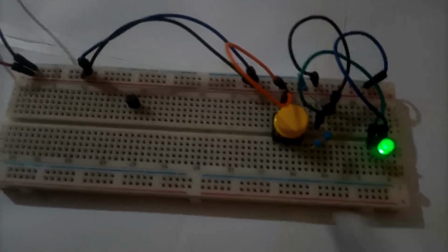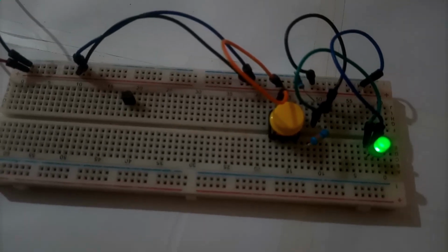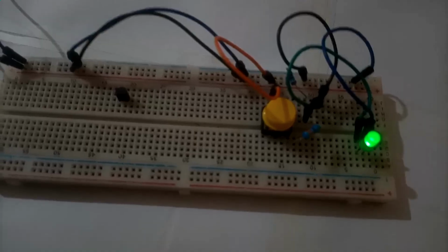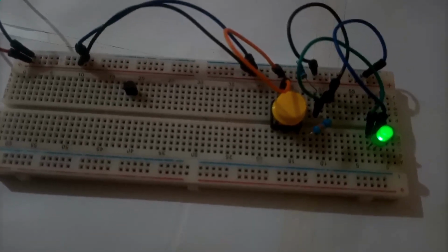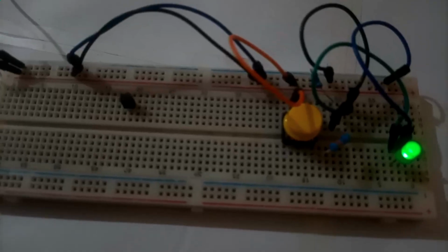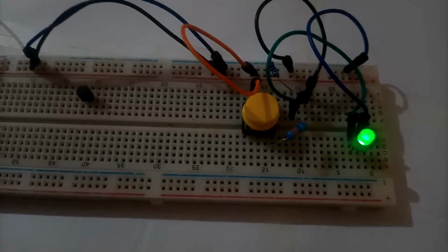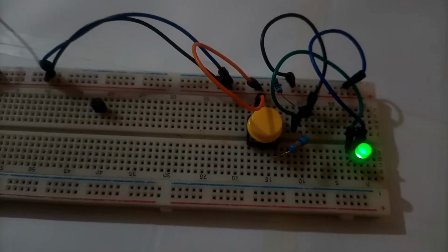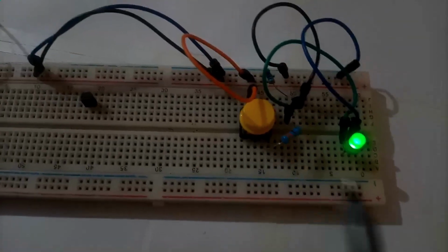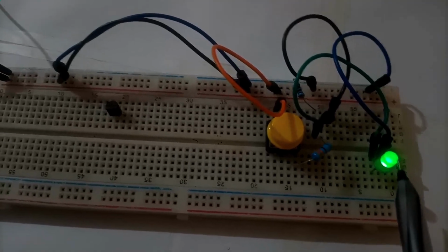If you give it true, it gives you back false, and if you give it false, it gives you back true. And true and false in computation is 0 and 1. That's the representation. So in this circuit, we're gonna use this button as our input. Currently we're not pressing it, and if we're not pressing it, that's a 0. And as we can see, we are not pressing it, and the light is giving us, the output is 1, or rather true.